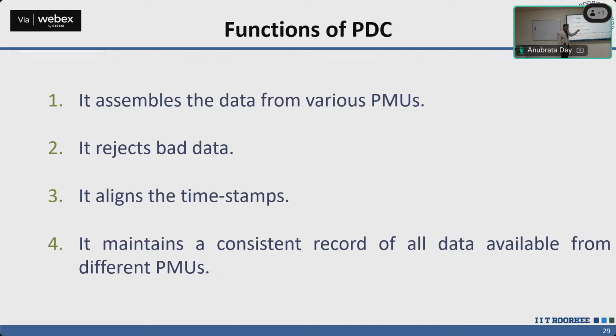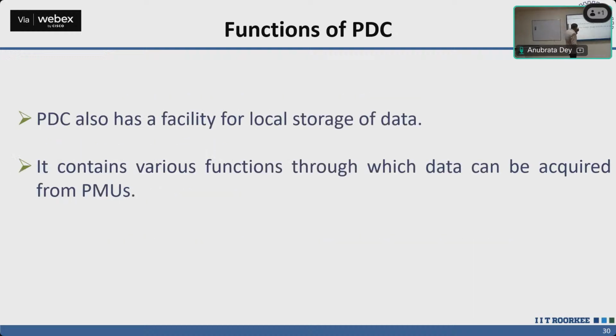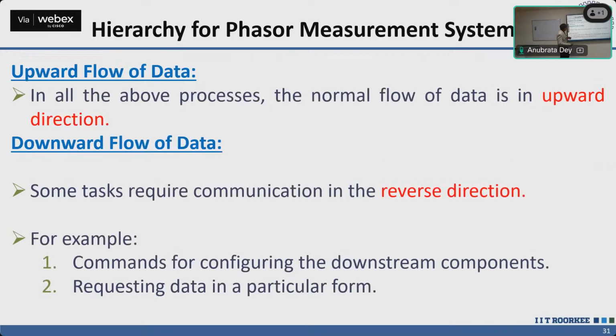It aligns. Time stamping is also done by the PDC. So the PMU never does timestamping. Timestamping is always done by the PDC. And then it is also going to maintain the records of all the data, so that if something goes wrong, if any postmortem analysis is required, then that can be done. Of course, it has some storage facility and all.